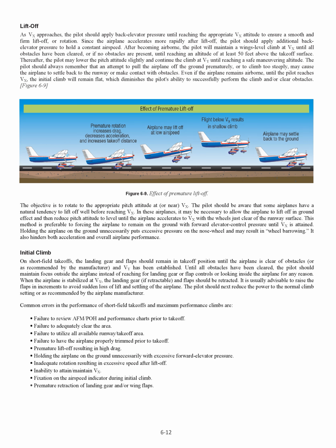Liftoff. As Vx approaches, the pilot should apply back elevator pressure until reaching the appropriate Vx attitude to ensure a smooth and firm liftoff, or rotation. Since the airplane accelerates more rapidly after liftoff, the pilot should apply additional back elevator pressure to hold a constant airspeed. After becoming airborne, the pilot will maintain a wings level climb at Vx until all obstacles have been cleared, or if no obstacles are present, until reaching an altitude of at least 50 feet above the takeoff surface.